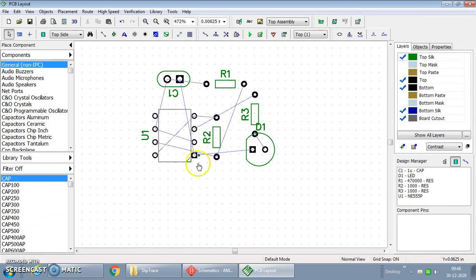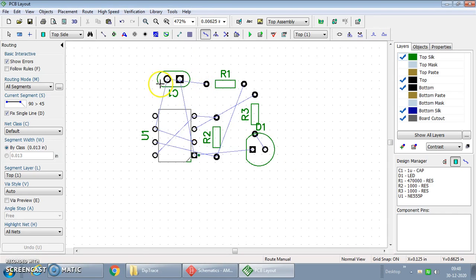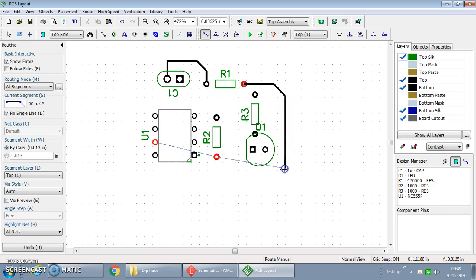Now, after this, our objective is to design the tracks, or the actual layout. While designing the tracks, there are options. If you go to this, route manually is also an option. If you do the routing manually, wherever we want to do the connections, suppose I want to do the connections from this point, I will go here, come down and do the connections here. So manual routing is also possible wherever the connections are required. Suppose I need to do the connections, I will come from this side and do the connection. The only thing is that overlapping of the tracks should not be there. It should be done properly.